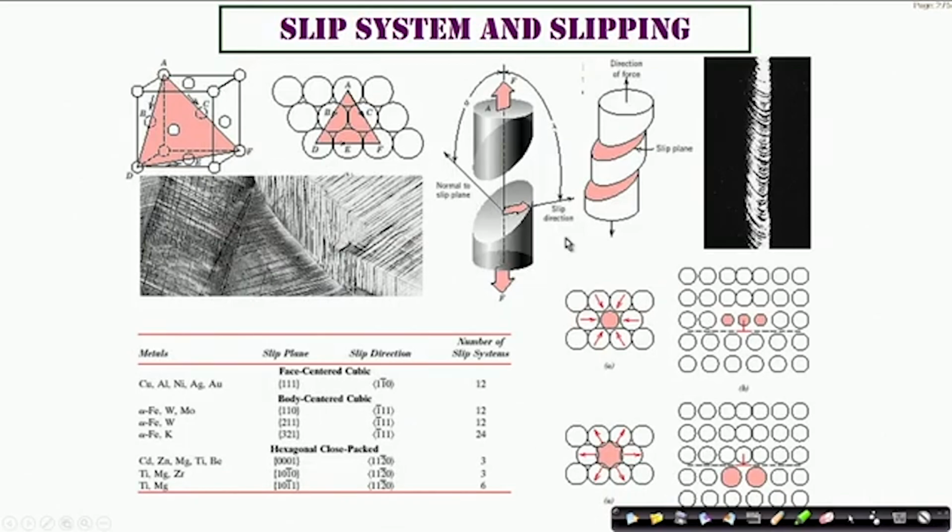And these dislocations, either edge or screw, are very important because they account for the deformation or shape change of all crystalline solids, particularly the metallic crystals, because deformation using such line defects is energetically always more favorable, since it requires a lesser amount of shear stress compared to a situation where the crystal is perfect. So the defects have a role to play not only in defining the stability but also in defining certain characteristics, such as deformation behavior or, in general, bulk or surface properties of the crystal.